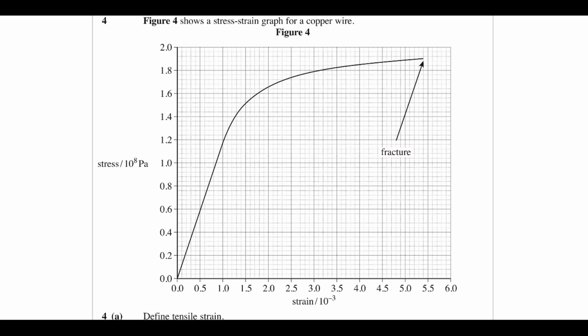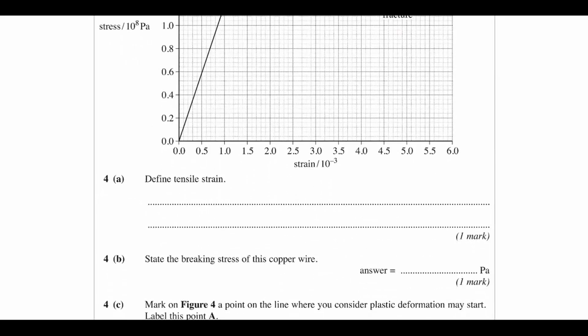We've got an ultimate tensile stress or breaking stress at this point where it fractures here, and we've clearly gone past the elastic limit somewhere up here to get plastic deformation. So that's the kind of features I can see there. So let's see what it wants us to do.